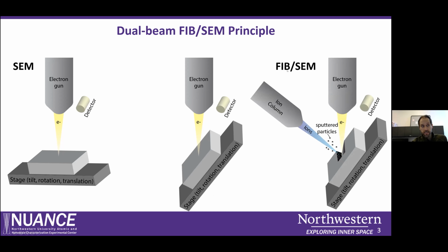So that's hence the term focused ion beam, which can shoot high energetic ions onto a sample and sputter away atoms in your sample, so sputter particles. And then the SEM can, for example, serve as imaging a cross-section of your sample. So you can selectively remove specific atoms at this selected area of interest.